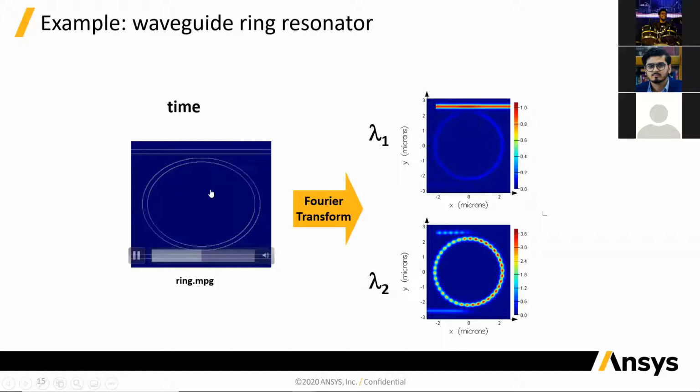So the way the ring works, as I mentioned, if you inject light of different frequencies on this waveguide, only at certain frequencies does the light from the waveguide couple with the ring here. And that depends on the group index of the ring and the radius of the ring. So at particular wavelengths, light would simply go through and not couple with the ring here. But at other wavelengths, it will couple to the ring, and then you'll see light entering here.